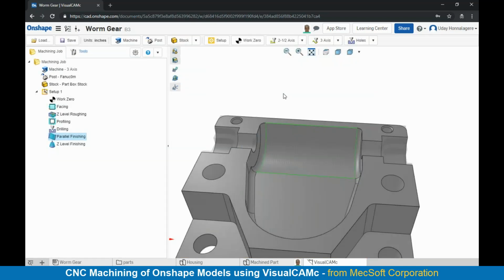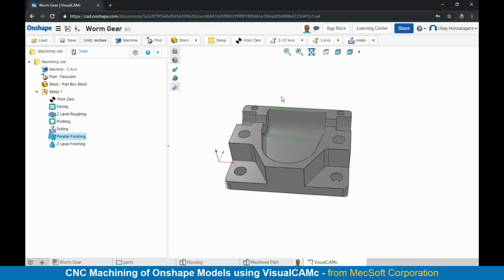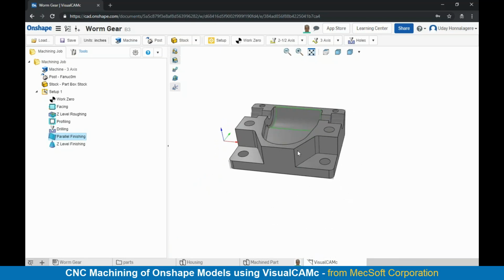programming window. Now once you have all these toolpaths and operations programmed, the final step is we need to communicate this to your machine tool. So we do that by a process called post-processing. And like we've already selected a post-processor at the start of your programming workflow in here, we can post it out to the machine tool.